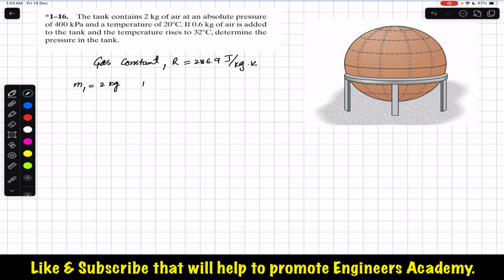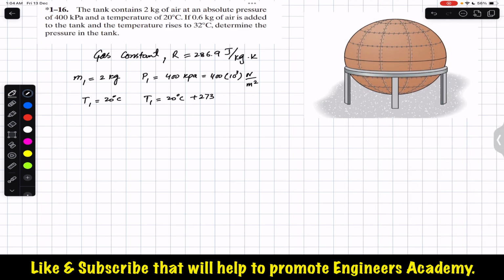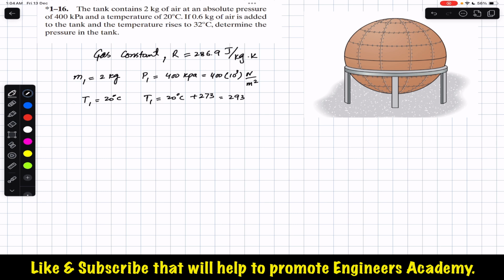So initially the mass in the tank is, let's say, M1, which is 2 kgs, and the pressure P1 is 400 kilopascal. So 400 kilopascal is equal to 400 kilo is 10 raised to power 3 and pascal is Newton per meter square. And initial temperature T1 is 20 degrees C. So T1 in Kelvin will be equal to 20 degrees C plus 273. So 20 plus 273 is 293 Kelvin.